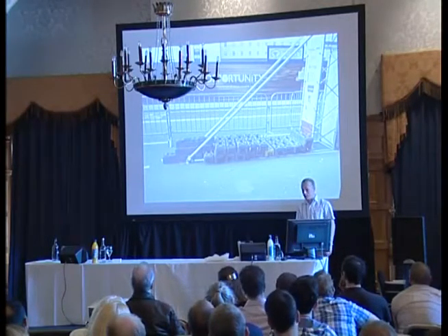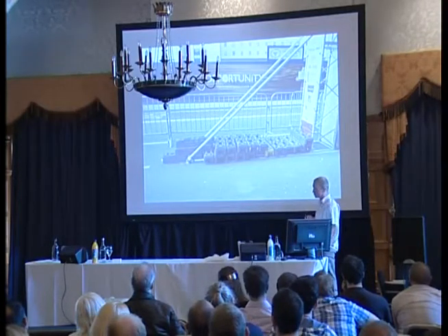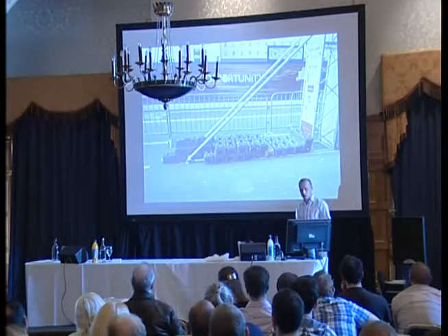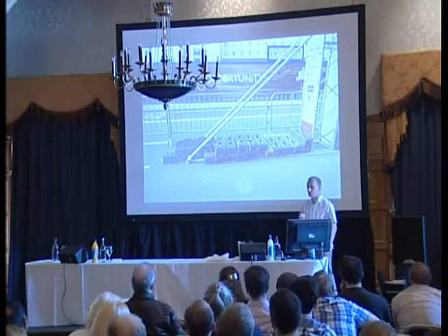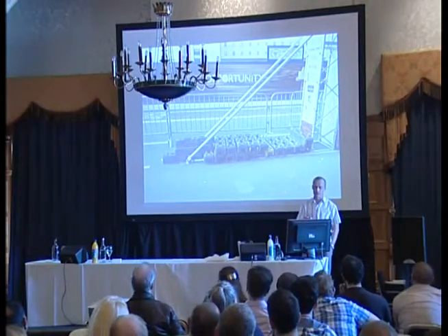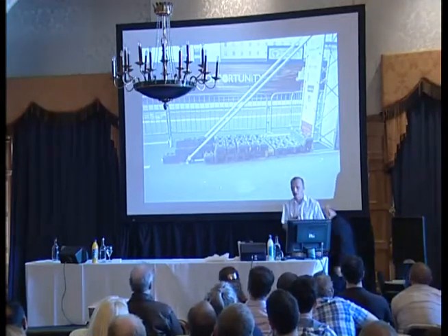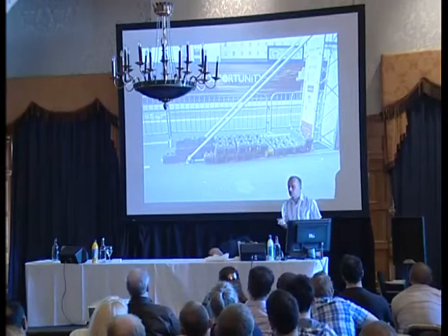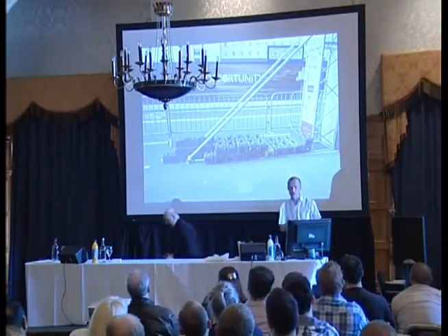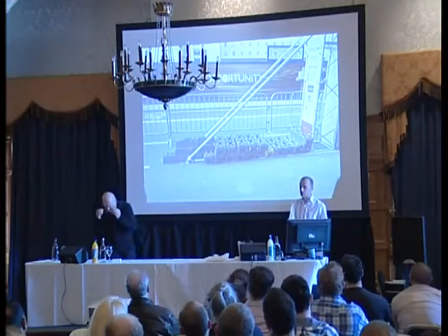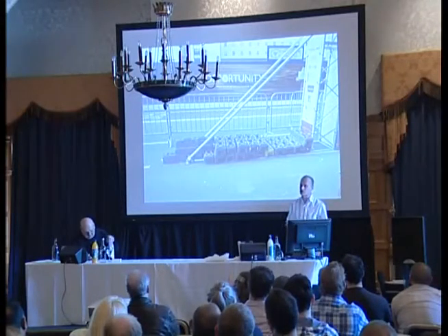Adding up the weight of all those rubber feet, which are probably meant to be concrete feet, and going back to the engineering calcs from the people who built this gantry, it says there has to be X number of kilograms on the feet. That's the piece of information that I need, because if it only needs 50 kilos, and each rubber foot weighs this amount, I can count them up and go, okay, you've got the right amount of ballast on the bottom.